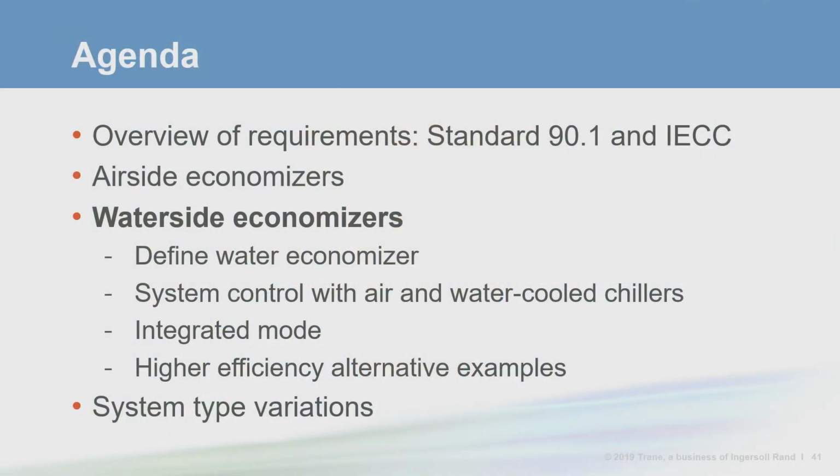Next up, Susanna is going to discuss waterside economizer design and control. This section builds on information provided in 2 engineers' newsletters. They are also included in your bibliography. I'll start with the most common question we get, how to control waterside economizers, which are sometimes called waterside free cooling. It's dependent on a lot of factors, so we'll go through an example. Then I'll discuss some of the pitfalls we see when trying to continue the free cooling cycle too long. Following that, I'll show an example calculation for how to meet the higher efficiency exceptions using air-cooled and water-cooled chillers.